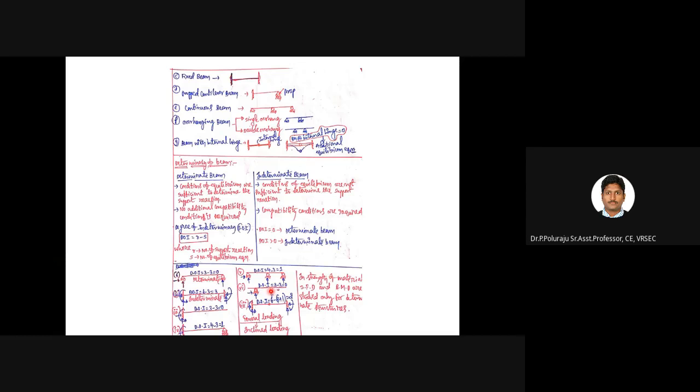In the types of beams, if you see here, out of these four types of beams, which is accepted? Only the last one is accepted because you are supposed to show one side hinged and the other side roller. Even in the note you can read very thoroughly. In a simply supported beam, one end should be hinge and the other should be roller in order to resist any horizontal load and so that no thermal stress develops. Then cantilever beam is one side only fixed and the other side is free.